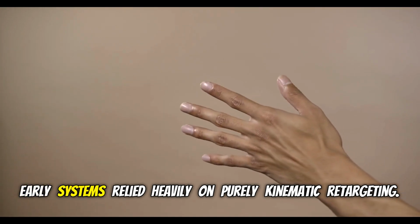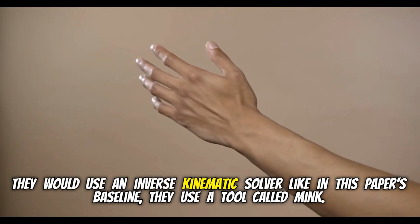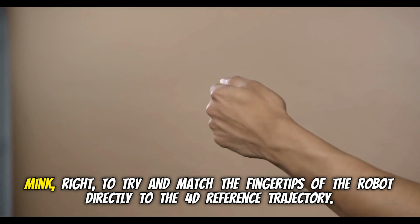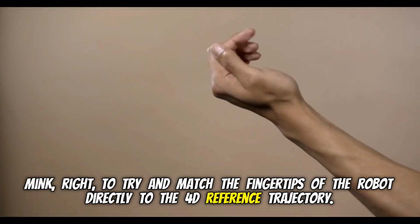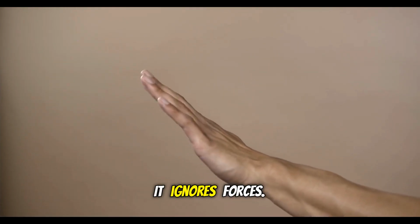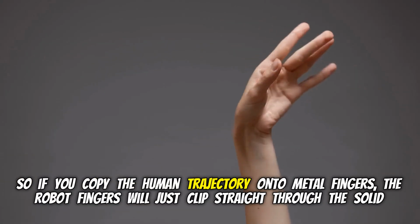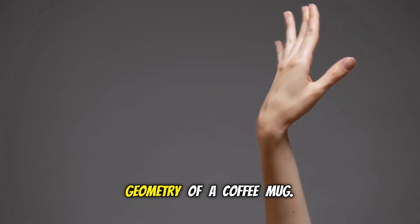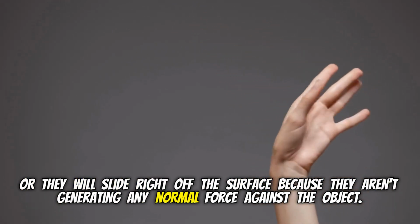100%. Early systems relied heavily on purely kinematic retargeting. They would use an inverse kinematic solver, like in this paper's baseline, they use a tool called MINK. MINK, right, to try and match the fingertips of the robot directly to the 4D reference trajectory. But kinematic retargeting is totally blind to physics. It ignores forces. It ignores rigid body collisions. So if you copy the human trajectory onto metal fingers, the robot fingers will just clip straight through the solid geometry of a coffee mug. Or they will slide right off the surface because they aren't generating any normal force against the object.